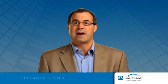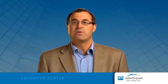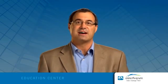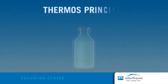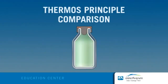When the interior heat tries to escape to the cold outside during the winter, the low-E coating reflects the heat back inside, reducing the radiant heat loss through the glass. The reverse happens during the summer. To use a simple analogy, low-E glass works the same way a thermos does. A thermos has a silver lining, which reflects temperature of the drink it contains back in.